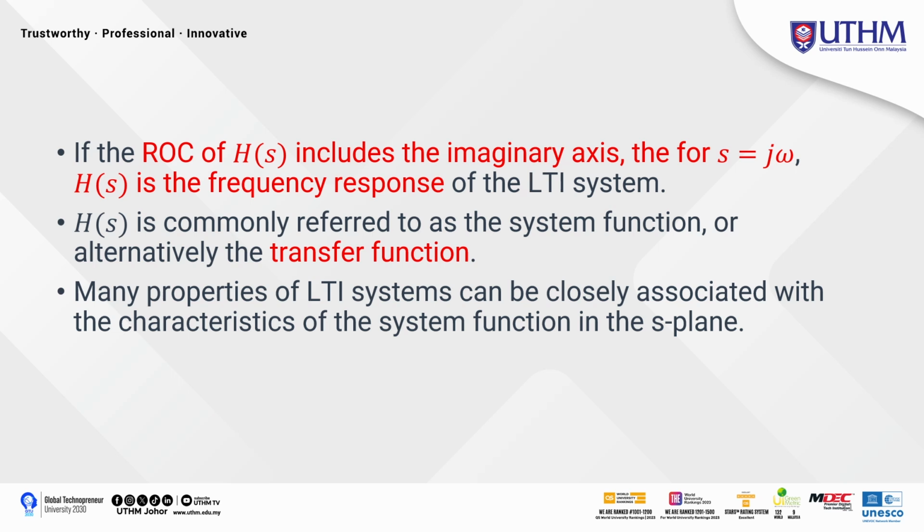So when we substitute s equal to j omega into H(s), the result is the frequency response of the LTI system. In simple terms, this tells us how the system responds to sinusoidal input at different frequencies. The function itself is called the system function, or more commonly the transfer function. It represents the input-output relation of the system in the s domain.